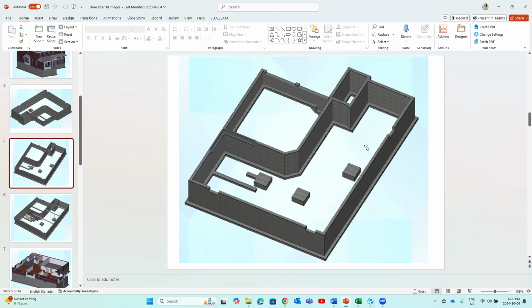Okay, formwork both sides. If you calculate concrete, you get the perimeter center line. Use the same perimeter center line. You multiply by thickness of the foundation wall, height of the foundation wall. You get the volume of the concrete, right? You also need to subtract those places. You see, you need to subtract volume of that. Formwork is we subtract the area, right? Area of this. Understand that, right? Formwork is subtract the area for both sides, right? That this situation would be only one side. This situation would be both sides.